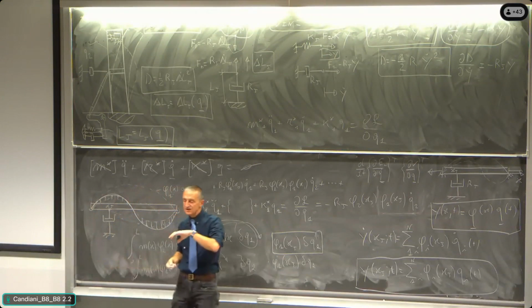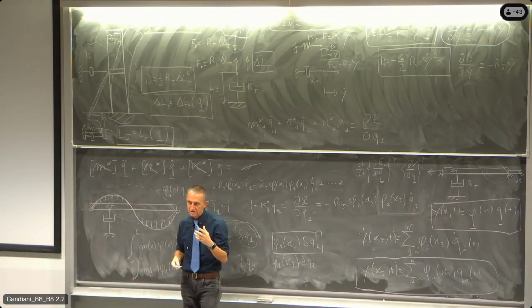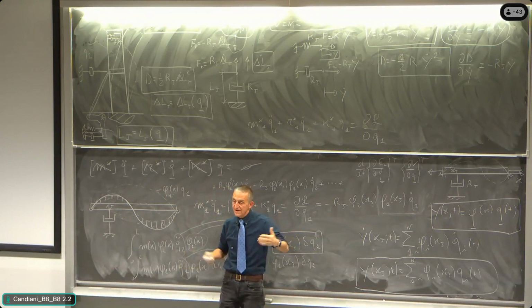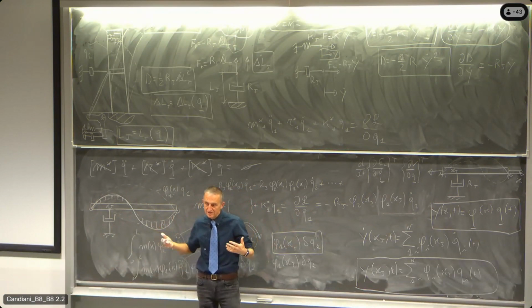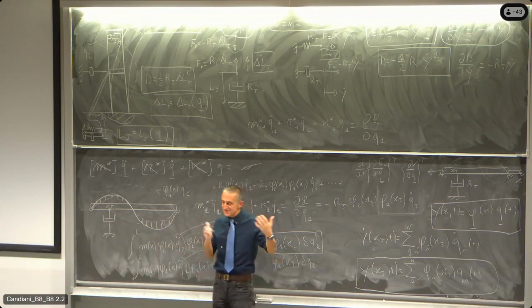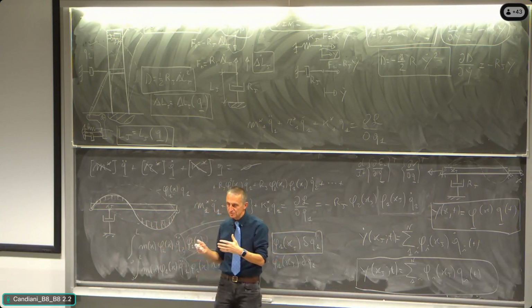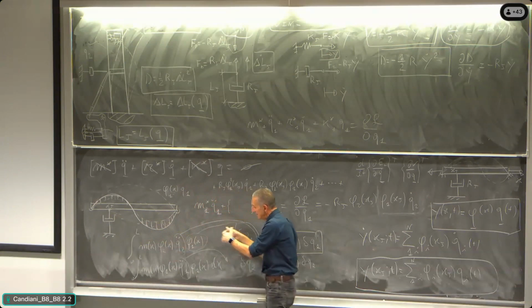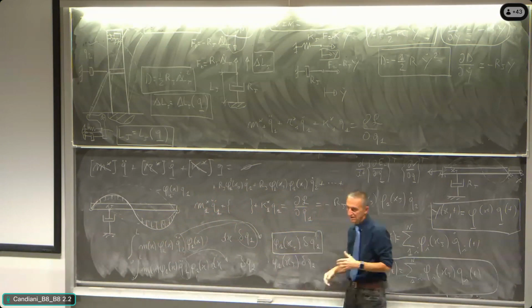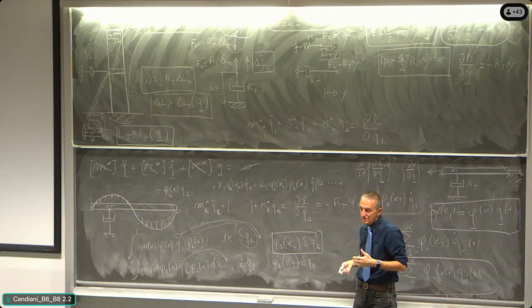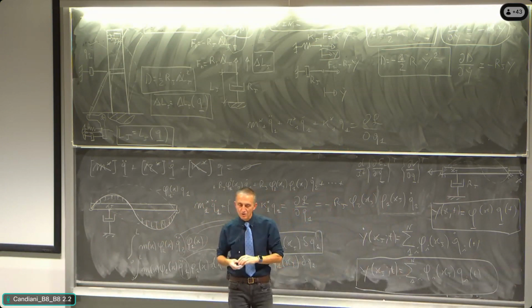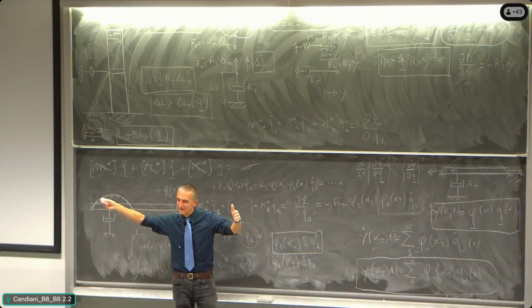And so there is this very simple hypothesis that is anyway reasonable to say that the distributed damping actions are somehow proportional to the mass distribution, somehow proportional to the stiffness distribution. And it happens that making the calculation in the way that we did, it becomes reasonable to justify what is appearing in real life.